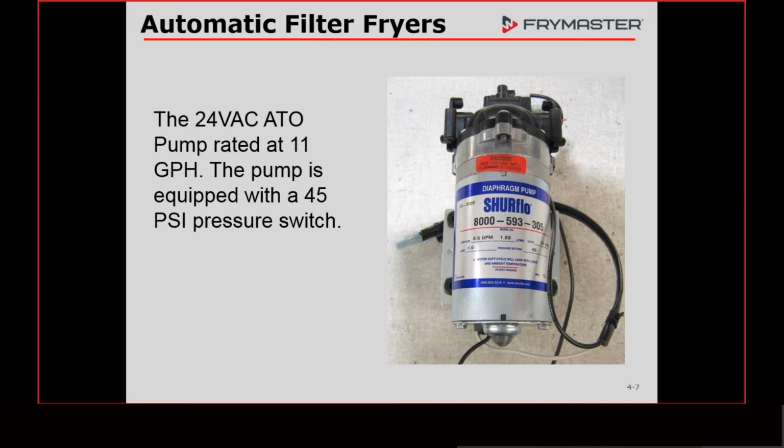You go back, you check for voltage, you're getting 24 volts to the pump, it's not coming on, automatically we assume we got a bad pump. We changed a lot of these pumps out, okay? Well, because we're changing so many out, we need to get them back and have somebody look at them, get them back to the company that makes them if we got an issue with them. Well, by the time we would get them back, the pumps worked when they got here.